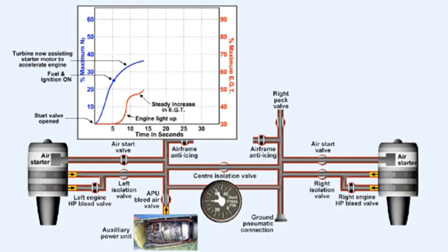The gas, which is being produced in the combustion chambers, now adds impetus to the turbine blades, which eases the task of the starter motor, and the engine continues to accelerate. The accelerating engine drives the high-pressure fuel pumps faster and faster, until they eventually manage to drive sufficient fuel through the fuel control unit, which enables it to supply the idle level of fuel flow to the burners.